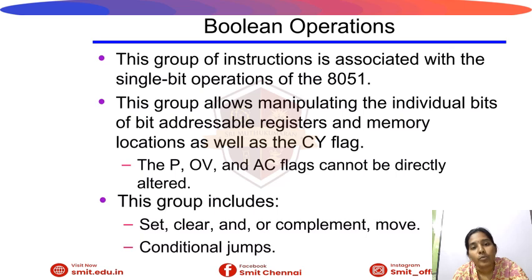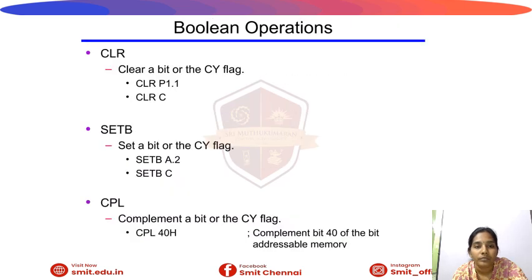Next instruction group is the Boolean operations. This group of instructions is associated with the single-bit operations of the 8051. This group allows manipulating the individual bits of bit-addressable registers and memory locations as well as the carry flag. This group includes set, clear or complement, move, and conditional jumps. CLR is the clear instruction, and to set the bit we can use SETB. CPL complements a bit.